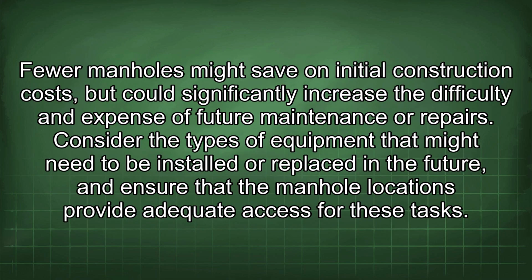Planning the layout of manholes requires balancing cost, convenience, and future needs. Fewer manholes might save on initial construction costs, but could significantly increase the difficulty and expense of future maintenance or repairs. Consider the types of equipment that might need to be installed or replaced in the future and ensure that the manhole locations provide adequate access for these tasks.